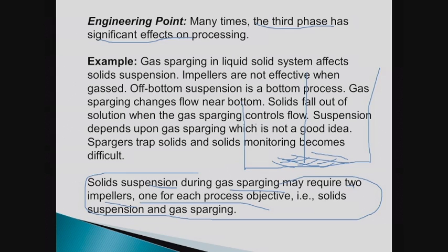So he built a very sophisticated computer model of how to operate the process, and what sort of design you would have to have for a good distribution of gas, with equal flow coming out of each hole in the sparge ladder or the sparge ring or whatever. And basically, he then took it to the plant. Okay. And the operation probably, I could be wrong, but probably only lasted for about 15 minutes before the sparge ladder was sanded in with the solids.